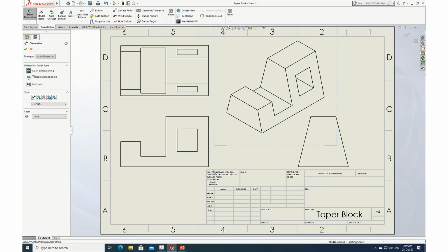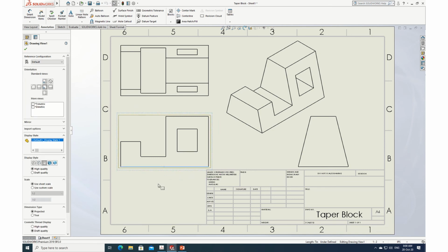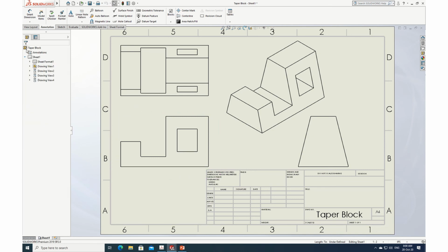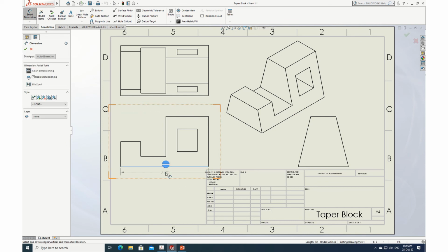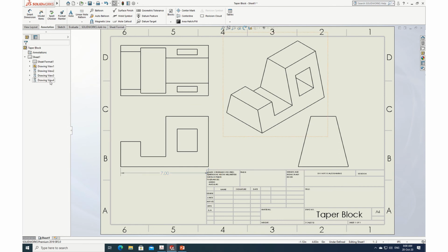So now go to Smart Dimensions. Under the annotate command, see here you have, oh sorry, I have to change it here to IPS. Now just go and select. I have selected IPS. Now let me go to Smart Dimensions. See 7. When it was in millimeter, it converted 7 inch into millimeter, and it was showing us there.